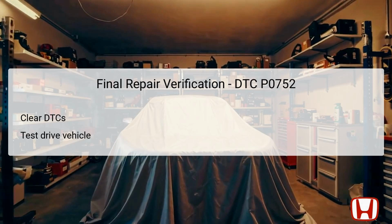This involves using the Honda Diagnostic System, HDS, to clear any stored diagnostic trouble codes that previously indicated malfunction. Once the codes have been cleared, the technician should conduct a thorough test drive to ensure the transmission operates correctly and to confirm that the vehicle no longer exhibits the symptoms associated with the DTC.